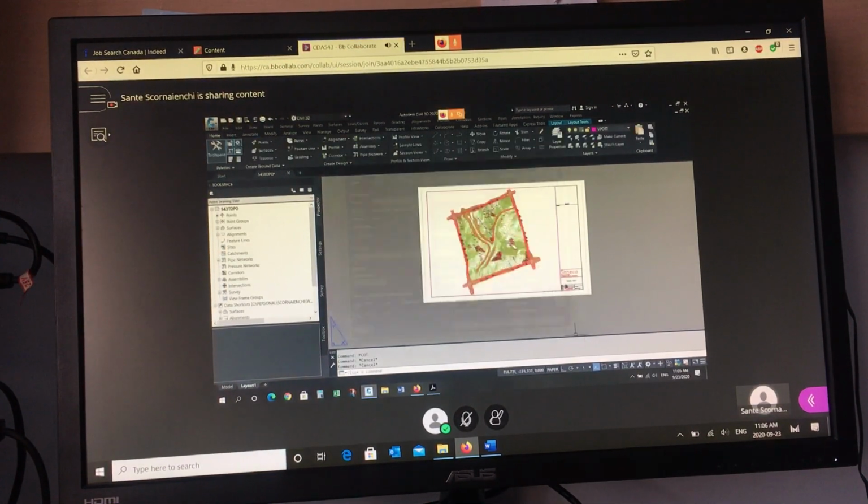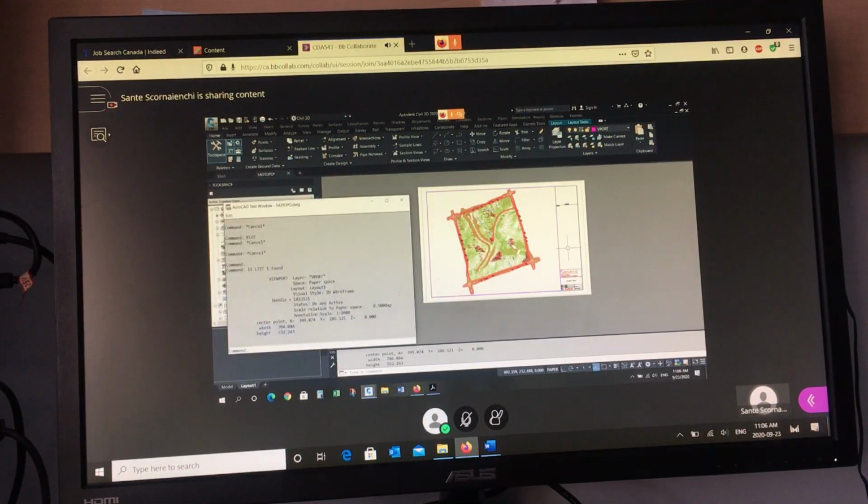But the zoom factor is half size. So if I list the frame, you'll see it's actually half: paper space is half of model space. Okay? And remember, 1/1000 is actually bigger than 1/2000. Right? So 1/2000, or 1 to 2,000, is actually half the size of 1 to 1,000.